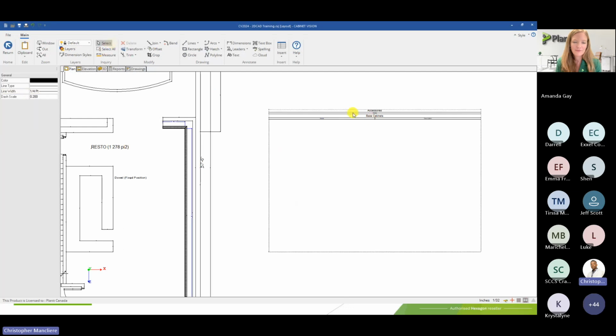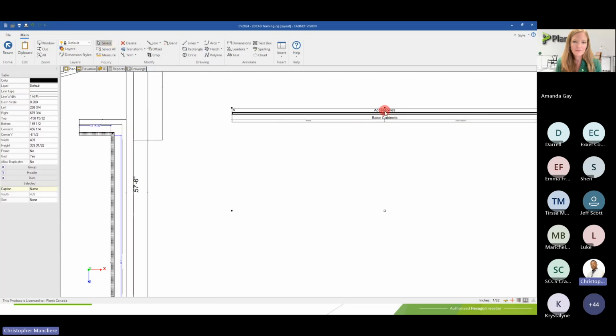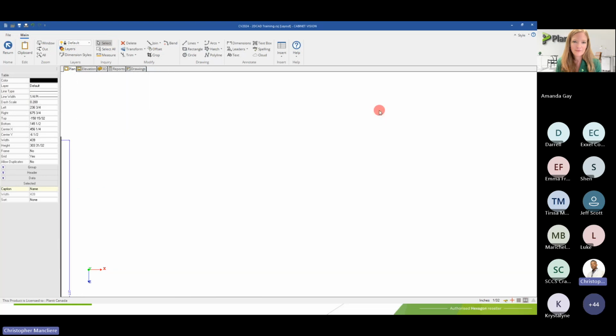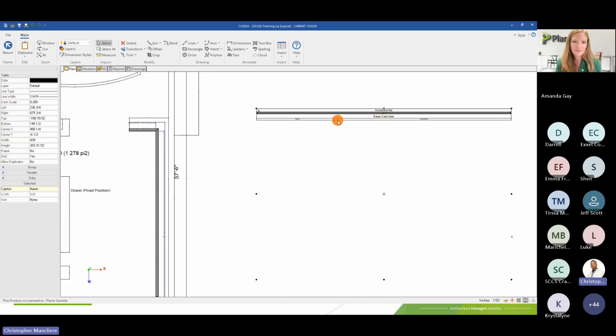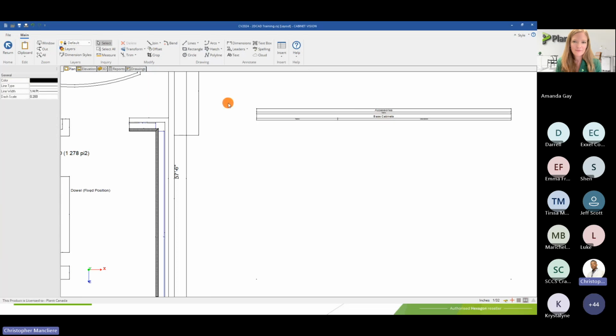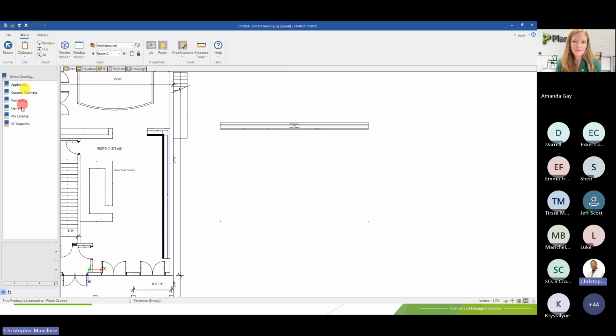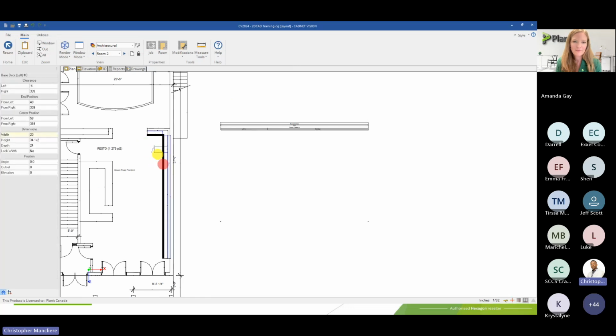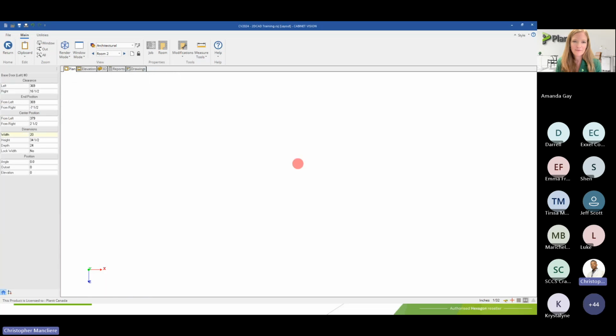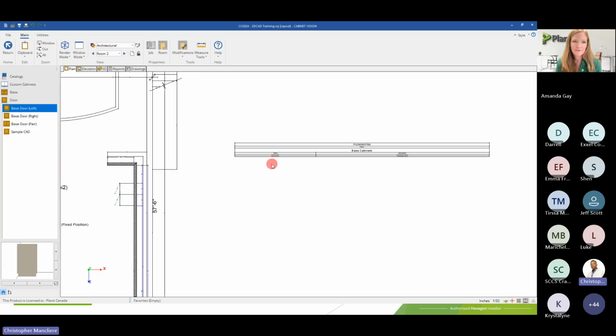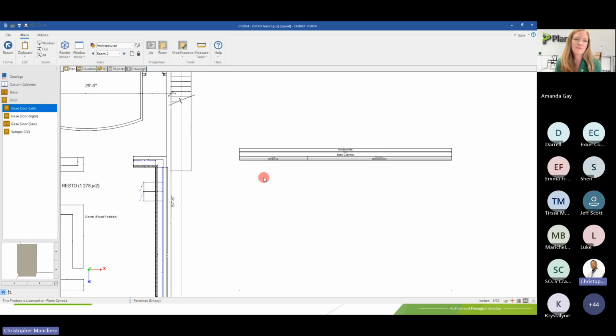And then this table, if you reselect it, you can format it. So you can change the title of the columns. You can change the width of the column as well. You can also right click and save it as a symbol if you want to reuse it. And as you add cabinets, for example, if I add a cabinet, my table will automatically be updated on my screen and be filled out here. Okay. And if this is still not enough, just go back to the recording and you will also go over more information on how to properly use the table.